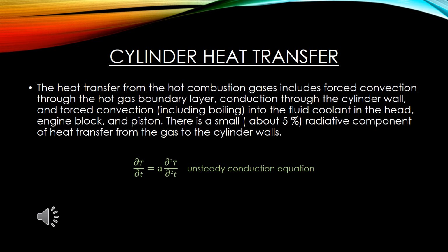Cylinder heat transfer. The heat transfer from the hot combustion gases includes forced convection through the hot gas boundary layer, conduction through the cylinder wall, and forced convection into the fluid coolant in the head, engine block, and piston. There is a small radiative component of heat transfer from the gas to the cylinder walls.